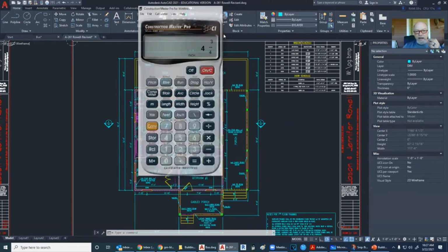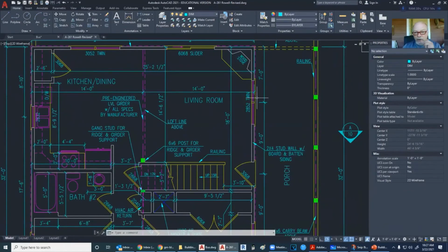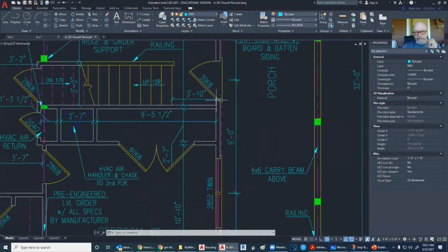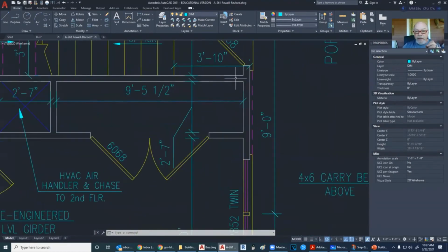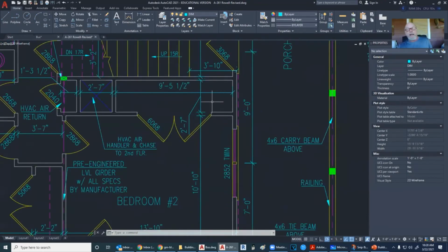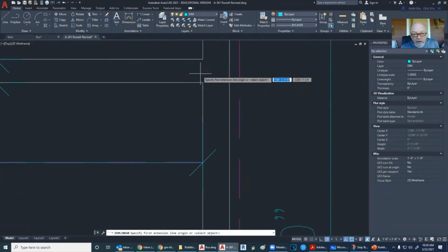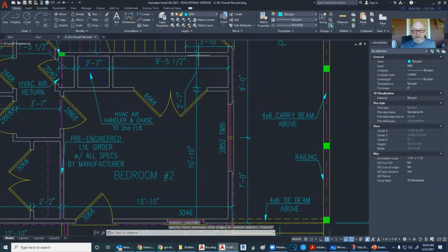So all I'm saying is, whenever you're laying out for the centers of your windows, for the centers of your doors, in between, in the old days we used to dimension to the center of the inside wall, which always ended up with 1/4 inch or 3/4 inch. But with CAD, you can't just grab the center of that wall because it's not going to give it to you. So we have changed over to doing face of wall to face of wall.